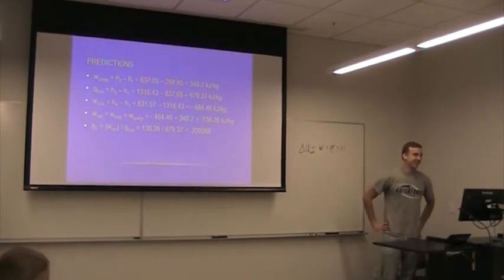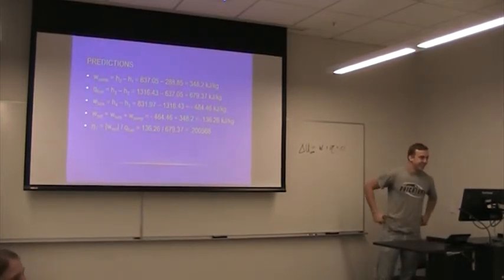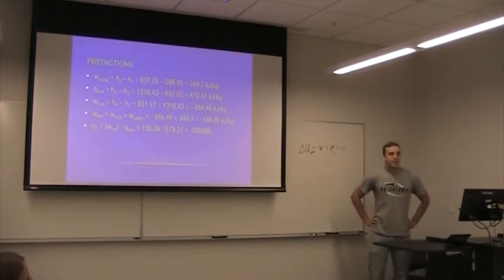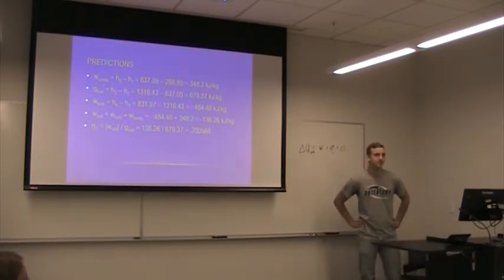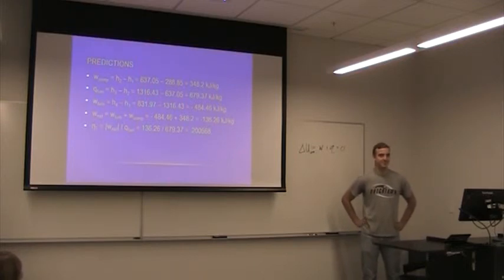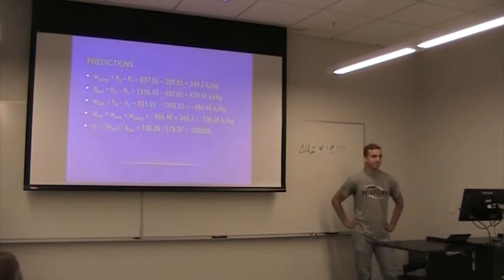No wonder. You know what you did? You looked up a website that's probably based in Europe. Written by a European, basically. In Europe, what you said is correct. If you get work from a system, it is negative. Work that goes into a system is positive. In the US, we do the opposite. If you get work from a system, it is positive. Work that goes into a system is negative. Right? And then the first law changes for us. Our first law is delta U is Q minus W. Right? And you wrote it down correctly, which is fine. So you remember that bit.